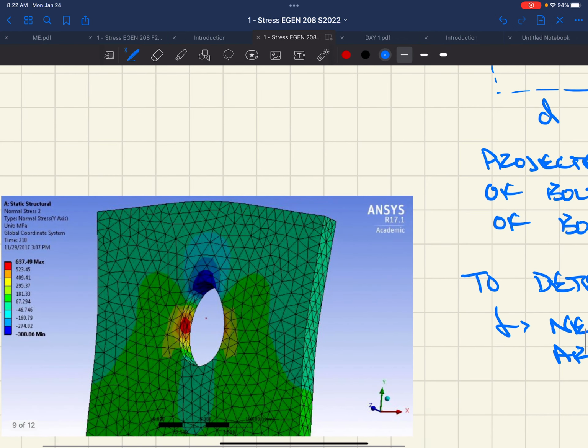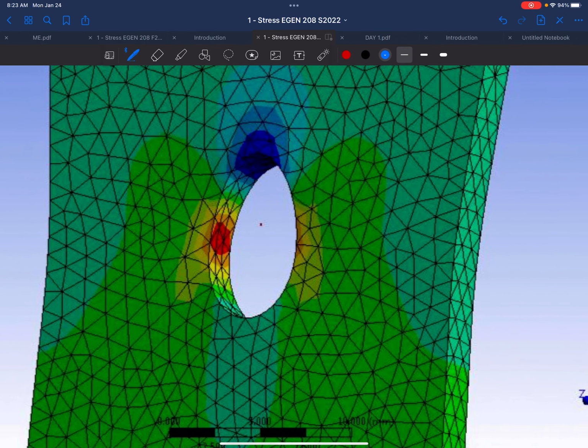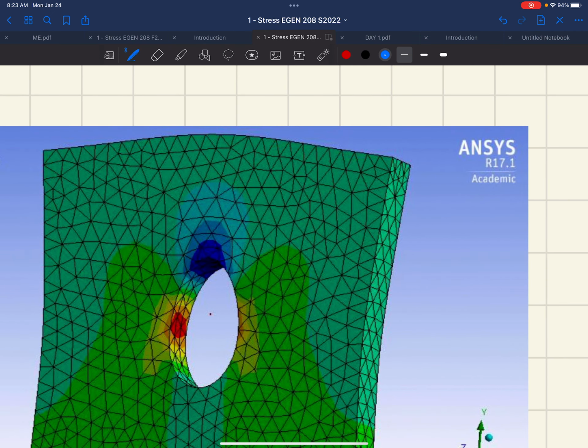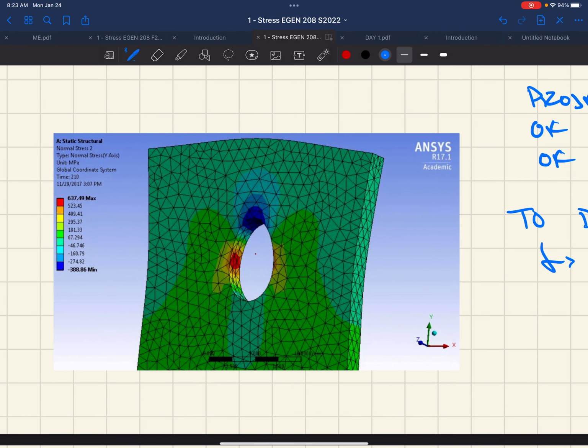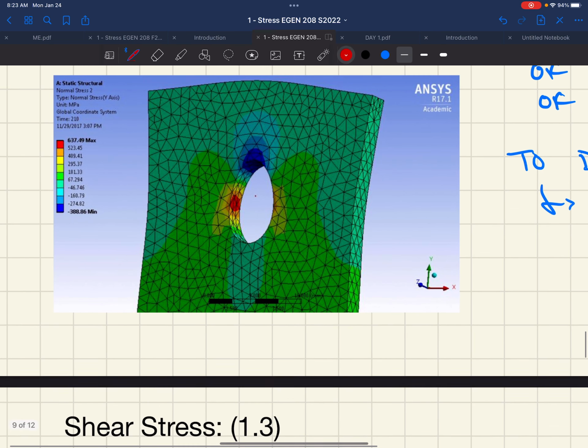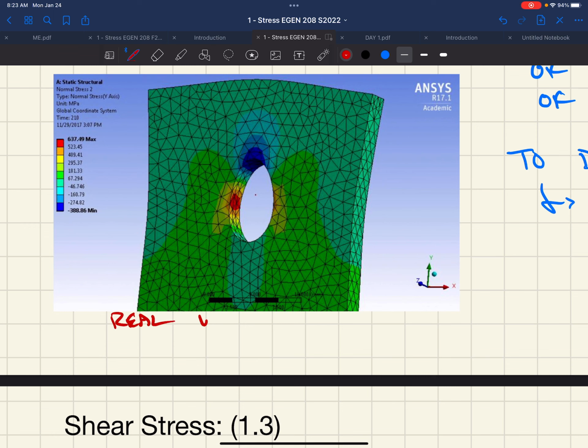The real world does something like this, where you would get some very large stress concentrations right where the bolt is contacting the plate originally. This is a finite element model. You will likely run into this, especially the METs, as you continue on if you haven't already. SolidWorks, this is ANSYS. But SolidWorks is a program that I'm sure some of you have had some experience with, but if not, you probably will in your time here. It's an incredibly powerful tool that essentially allows you to model a real world situation as close as you can, so you can get closer results and actual stresses. So this would be real world. It's more complicated.